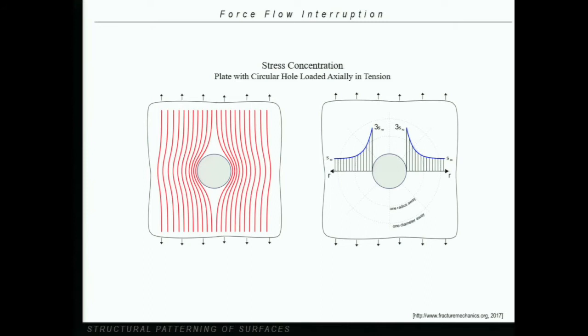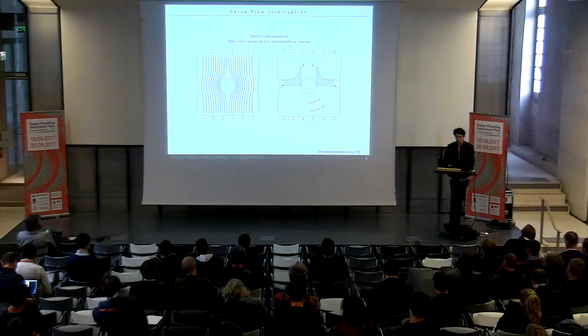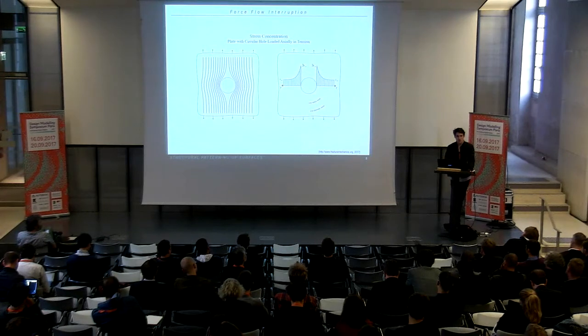Another simple heuristic to design patterned structures is to analyze the forces, the stresses in the base structures, and then nucleate apertures or scale pre-populated cells according to the stresses. The higher the stress, the smaller the aperture, and vice versa. The simplicity and ease of application of this rule is appealing, but unfortunately, this naive approach is misleading as holes disrupt the flow of forces in a structure, especially when they're large, rendering the initial stress configuration completely obsolete.